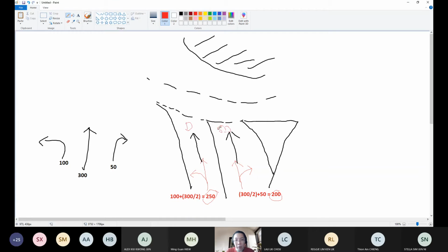All right. So if you have 3 lanes, same thing. You just have to make an assumption about the movement for that particular lane. If you have 3 lanes, then you have to make an assumption. Maybe this lane is only for left turn. This lane is for through movement as well as left turn, and this lane is for through movement and right turn. So if that is the case, the combination would be different. Then your total volume would be different.